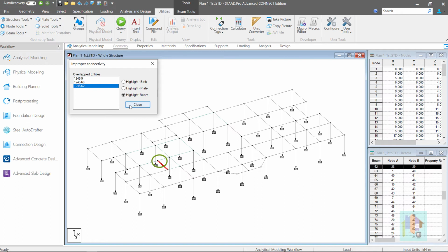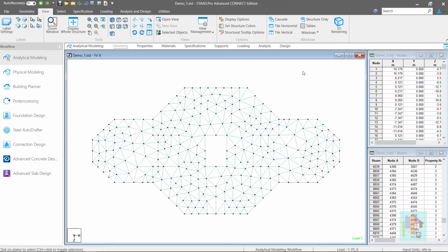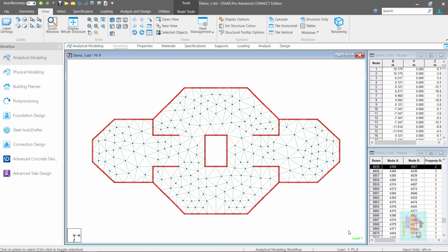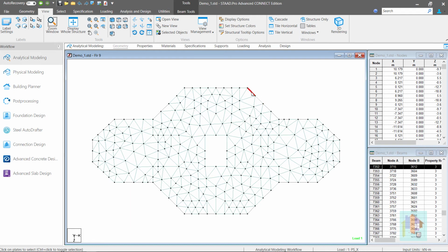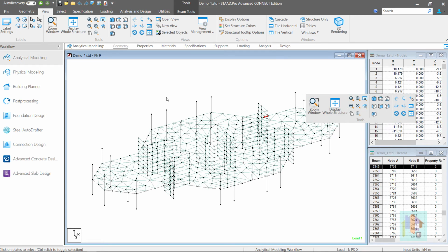the realistic scenario. Modeling of a plate will be proper only if the plate shares a common node with all the members and plates located in the adjacent area. This means any existing plate node or beam end must be selected as a corner node during new plate generation.